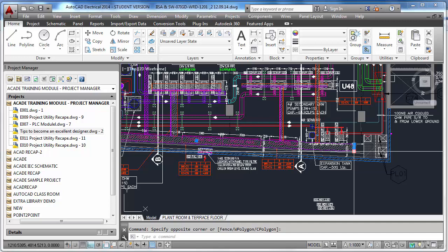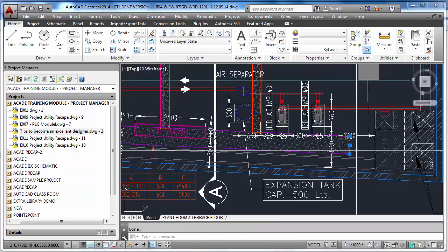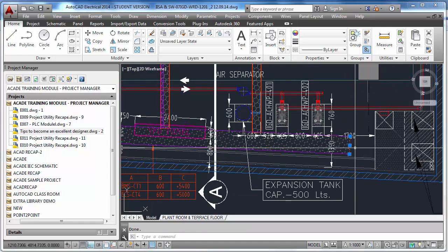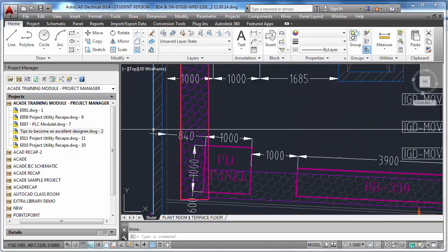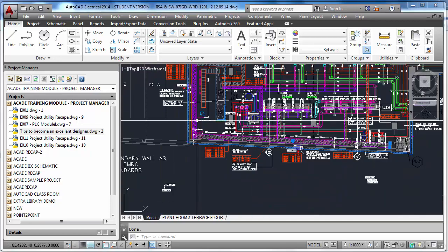They made it separately, merged it together finally and handed it over to me. Then they asked me to put my part, that is the cable tray, over this drawing. So I made these trays in a different layer, and I made only these cable trays, these hatch portions.